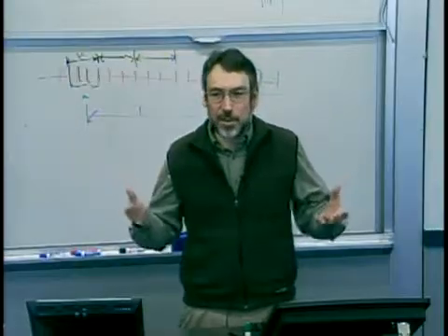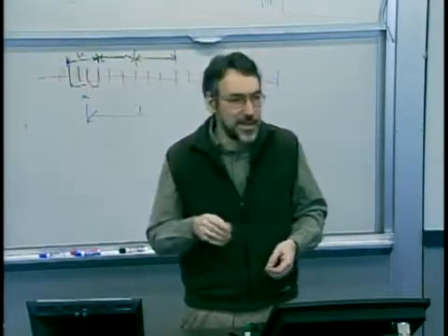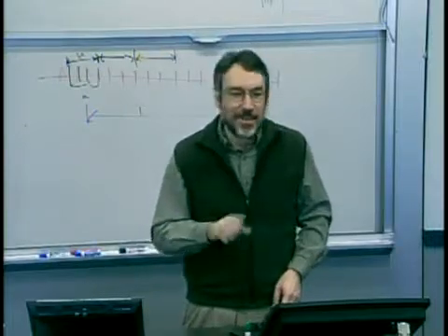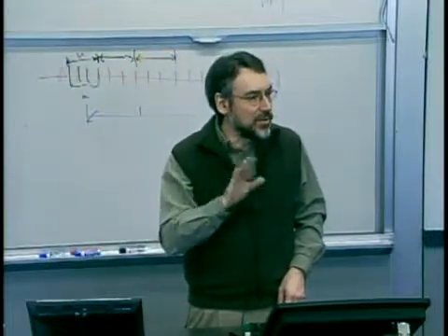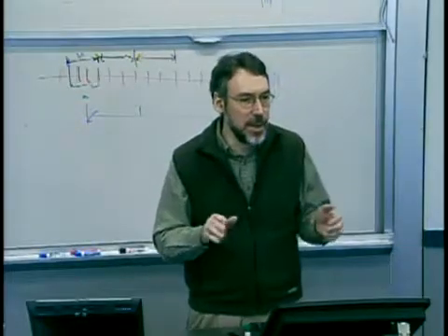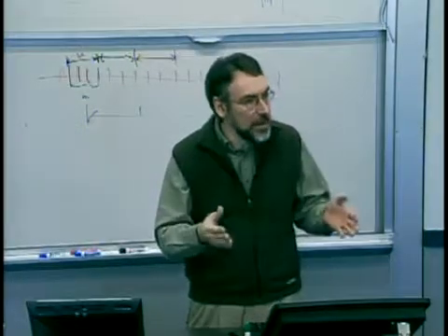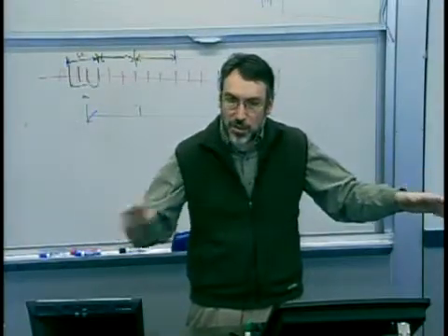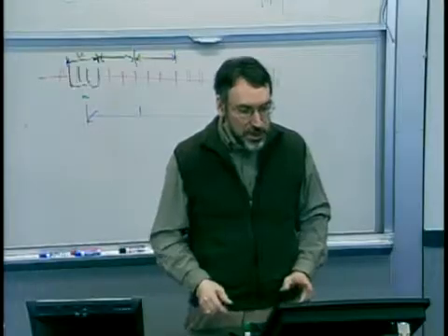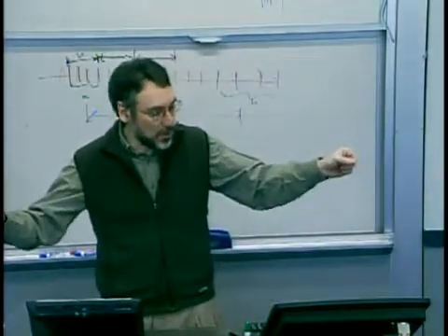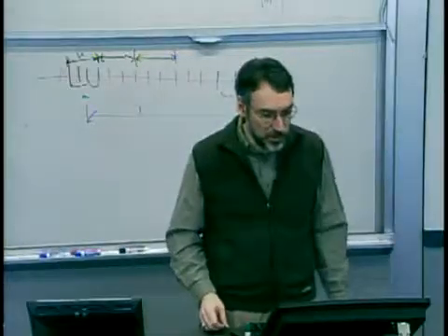Well, the larger, the better, right? A CP or CPK of 0, that's not good. When you start getting in the ranges of 2, that's often what is talked about in manufacturing as being a goal. But it really depends on your process and what the costs of non-conforming parts are, right? But just to give you a feel for these probabilities of non-conforming parts and what kind of CPs or CPKs those correspond to,